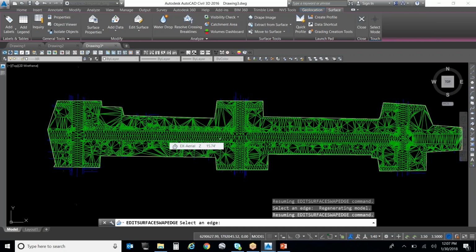So if your data is not that close, you might want a little larger margin so that it blends better, okay? Rather than just show a vertical edge of half a foot, okay? So leave like a gap. Leave a 3, 4, or 5 foot gap between your survey points, depending on how big the elevation change actually is, okay? So again, that's based on how much survey data you actually have.